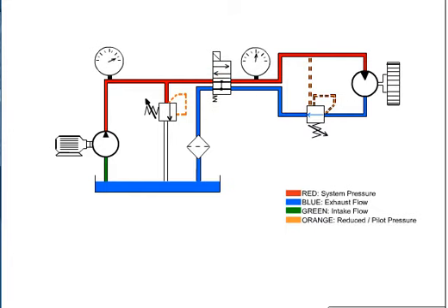When we de-energize the directional valve, remote pilot pressure is lost, allowing the valve to close. The inertia of the load will now drive the valve open via the internal pilot, giving us dynamic braking. Now that you understand the application of a brake valve, push Energize, then stop to see the valve function.